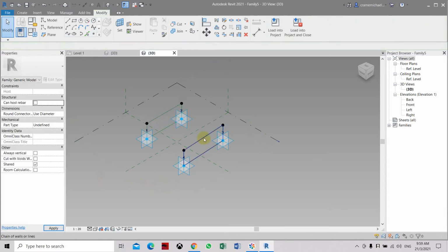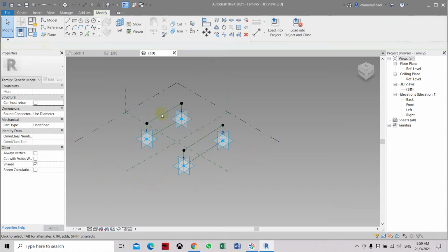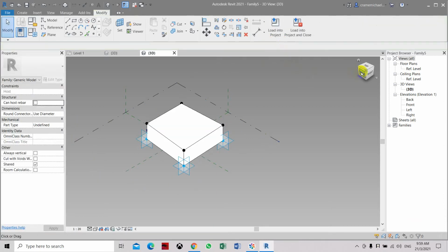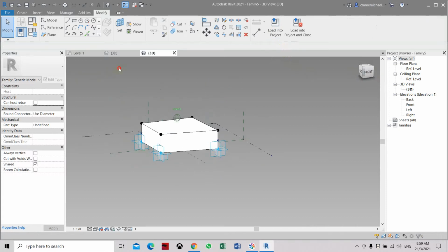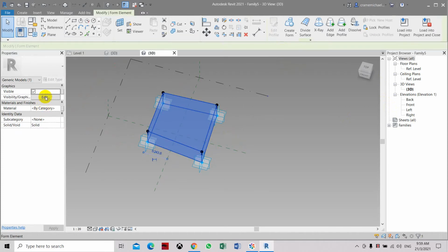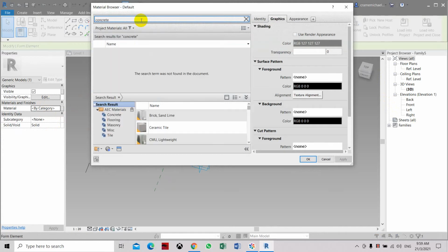So we can use it to create a point here. Select in reference line. Now select this first reference line, press Ctrl, select the second, and create form solid. Now you created a regular shape solid form with the thickness. Let's set this, it's going to be a material, concrete material. Let's see, a new lightweight concrete, let's set it as